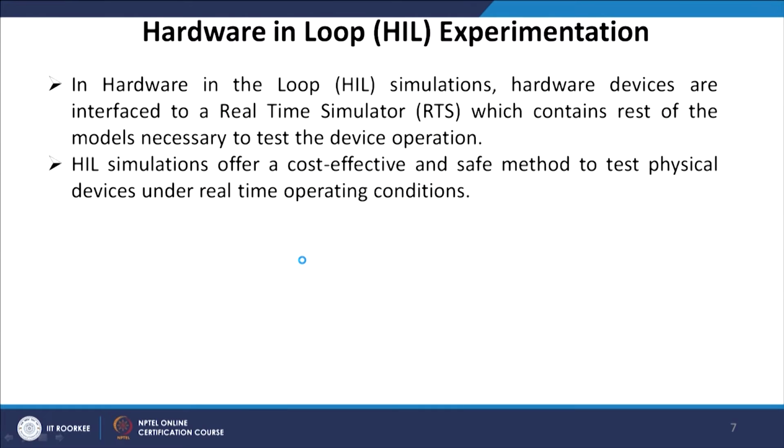Now, HIL simulation, hardware in loop simulation, offers a very cost effective and safe method to test physical devices under real time operating conditions. HIL simulations are of 2 types. One is the so called closed loop type and the other one is known as open loop type.